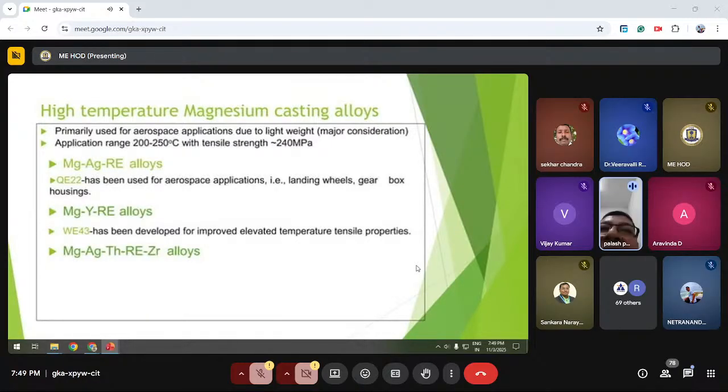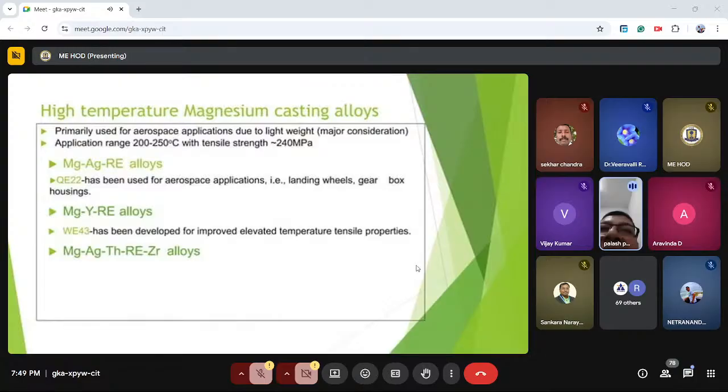Coating of magnesium alloys. Advantages of forged magnesium components compared to die-cast magnesium parts. The forged alloys show excellent strength, especially with the fibers aligned to the main loading direction. Very good property for pressure seal components because the forging process prevents a porous microstructure.